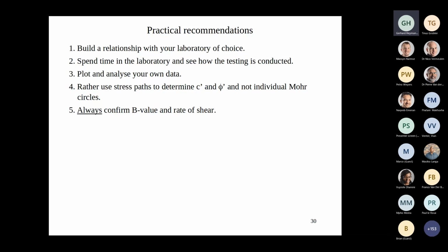And that is one of the main reasons why simple shear testing, I think, is going to make a significant comeback, because it was pretty popular in the 70s or so, especially in the research labs. But now with this whole issue of testing post-yield strain softening, particularly in tailings, where if you're doing triaxial, you're going to get shear banding, I think the simple shear apparatus is going to make a big comeback exactly for that reason, because in a simple shear apparatus, you do not get shear banding.